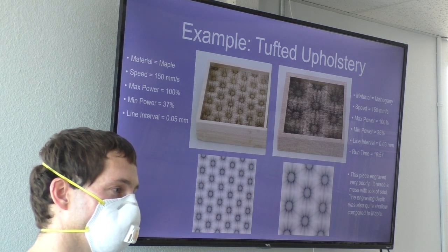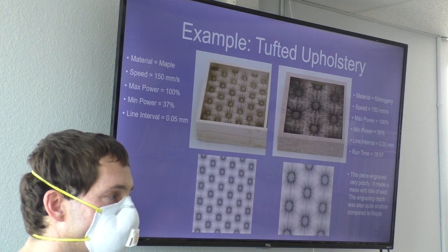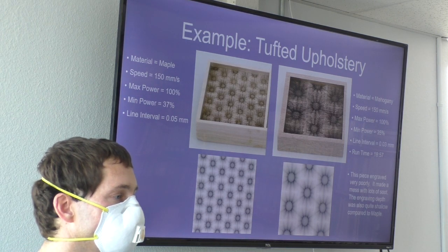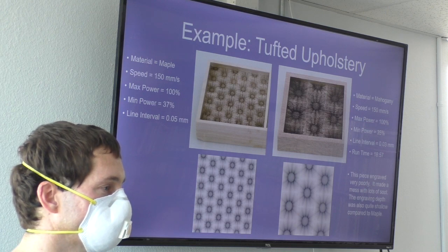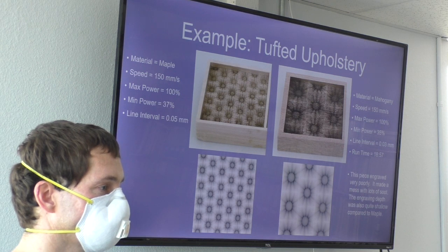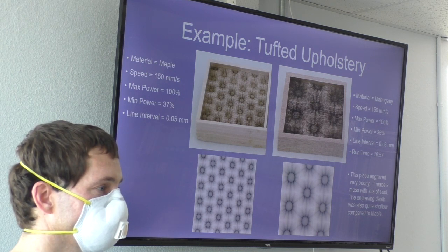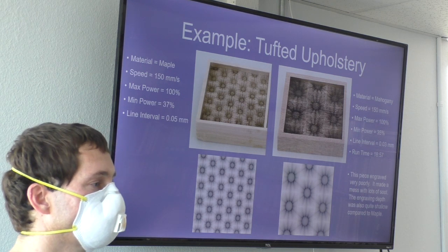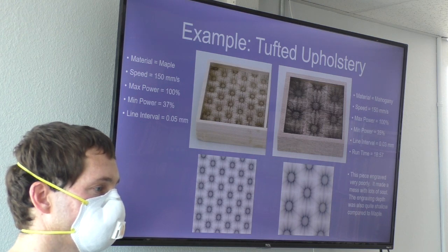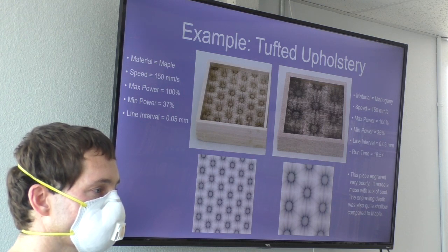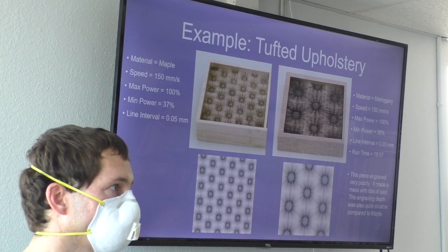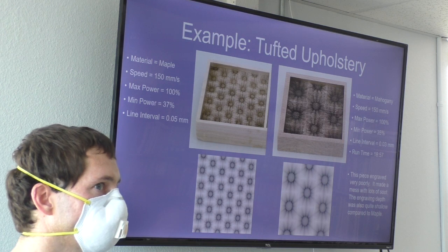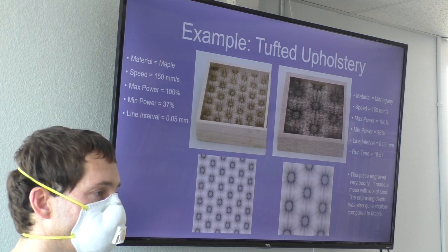Was that with a laser or with a CNC? Yeah. So I made them out of a CNC, obviously, but the logo said Mancala on top, or the city skyline and stuff. Those were done with my laser, and I had accidentally left it at a higher power than I thought I did, and I put crosshatch on it. So it was burning probably 1/8 of an inch deep. And I was impressed with how smooth the bottom came out. It came out very, very nice. And so that's been my experience with mahogany.